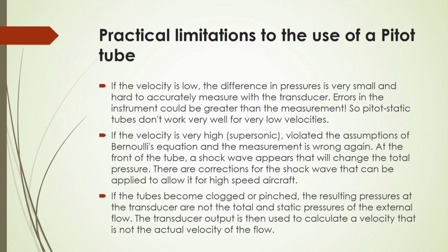And also you will see that if the velocity is very high, let it be supersonic, that means velocity is greater than sound velocity, then it violates the assumptions of Bernoulli's equation, and in that case the measurement would be wrong.